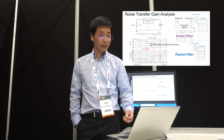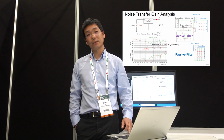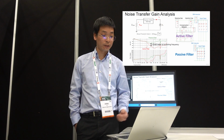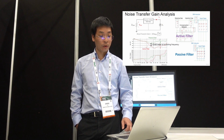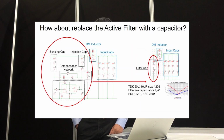So now we see this gain is really important, right? It has a physical meaning, and if you see the formula, it's V divided by I, so the unit is resistance. So this is an impedance concept. And if you look at the curve, this is very similar to what a capacitor can do: high frequency, low impedance, very similar to a cap. So natural thinking is, how about you replace this active filter with a cap, right? Then this is a fair comparison, because adding the cap is still a passive EMI filter, and we should compare those two cases.